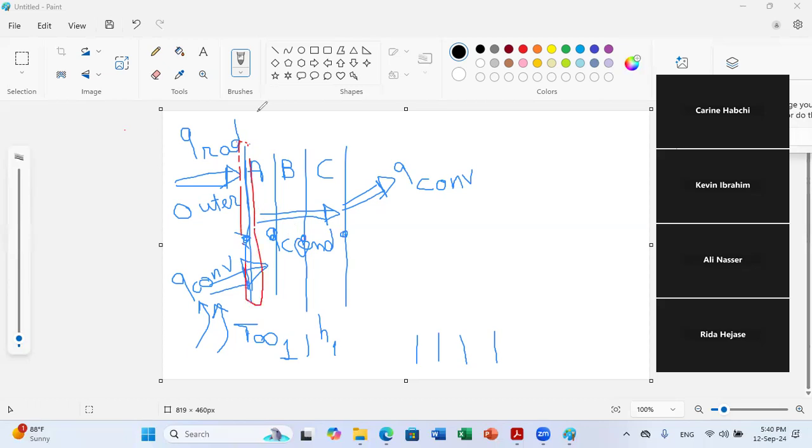And since this layer is of negligible mass, no storage, no generation, I always have for a thin layer the sum of Q dot in equal to the sum of Q dot out. So the rate of energy coming in equals the rate of energy getting out. And this will allow me to say that